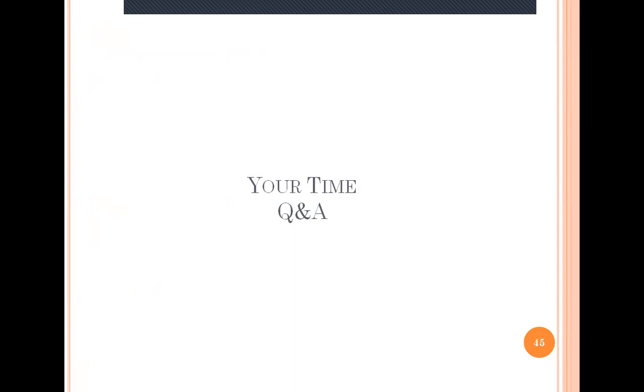The title of the session was all about pressure, right? But mud engineering, I think, also handles things other than pressure. For example, when the wireline logging company needs to do some kind of pressure test and needs to set the packer and so forth, the mud engineer usually spots sodium bromide or some kind of chemical across the zone that will be used as the packer setting location, to maintain the integrity of that section during a very long test, which could last days.